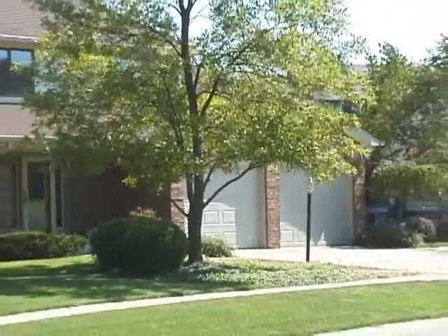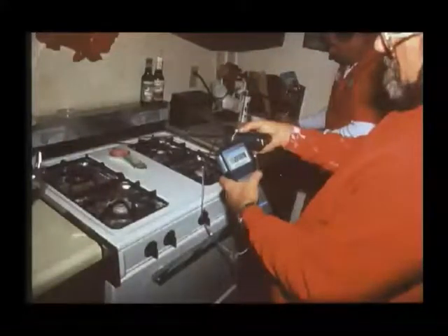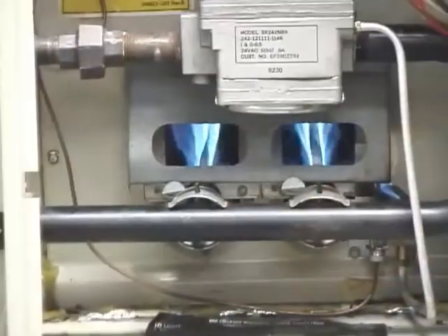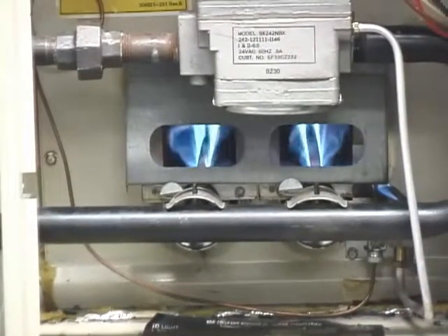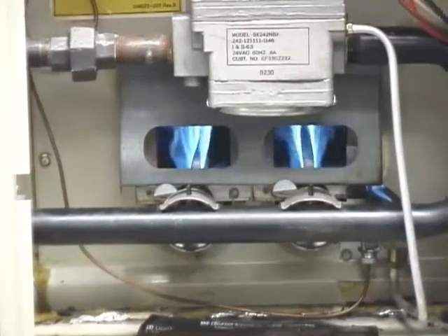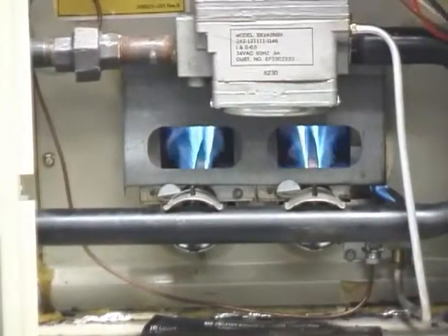While new research is finding that attached garages and unvented gas appliances such as gas ovens are more common sources of low-level CO production, when larger appliances like water heaters and furnaces don't vent, the result can be much higher and more immediately life-threatening levels of CO. Understanding the venting process and the many factors that can cause it to fail is essential for all those involved in inspecting and servicing residential gas and oil-vented appliances.